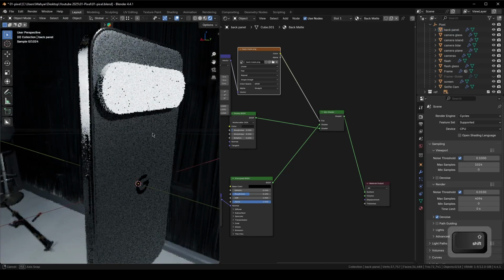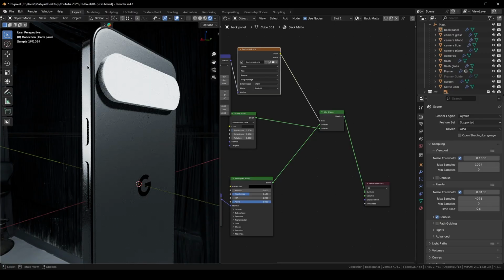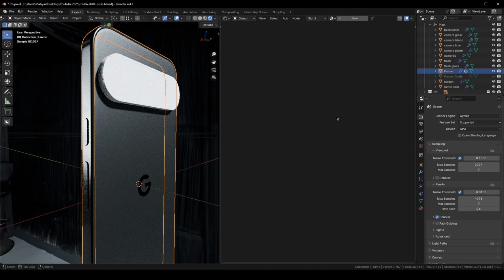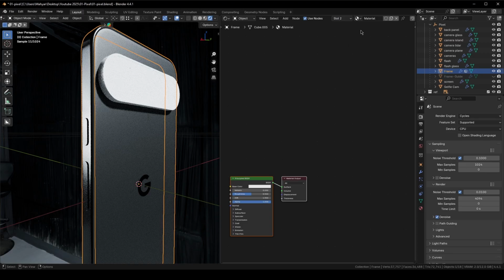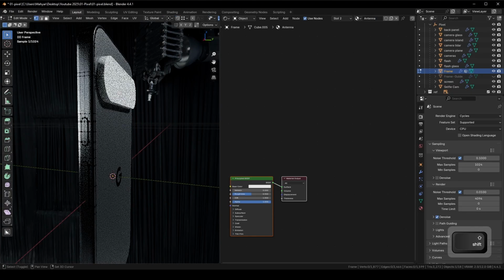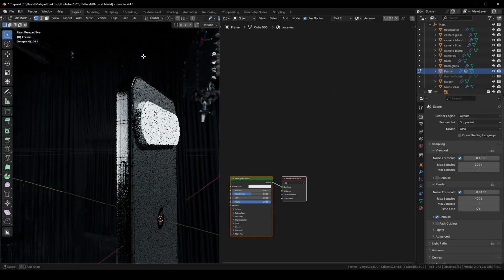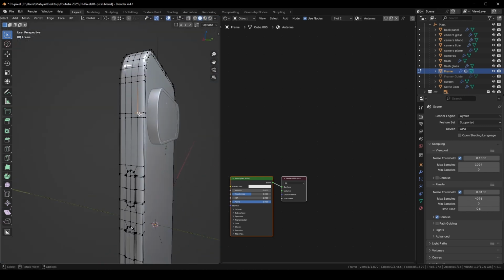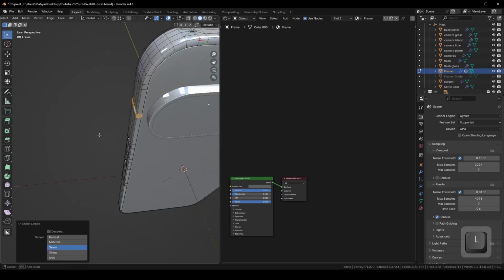Now I forgot to create the antenna materials here, the antenna cuts. I select the frame here, add a new slot, and rename it to create a material and rename it to antenna. I first need to select the antenna part. I go to the solid mode and select the parts I want to be antenna. Press L since they are detached.